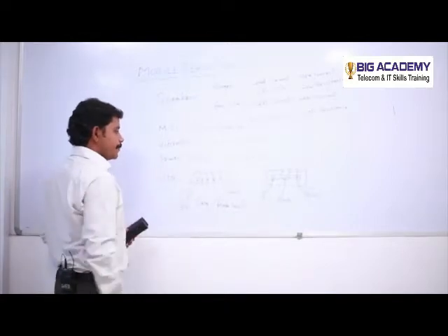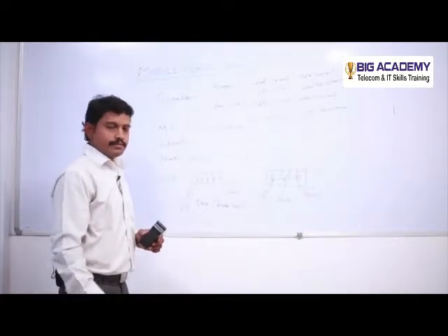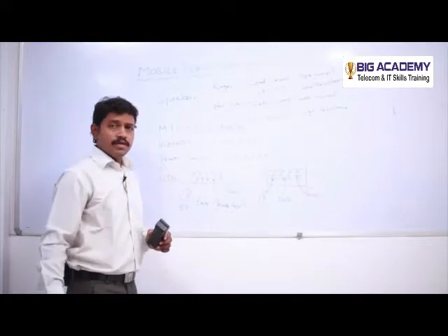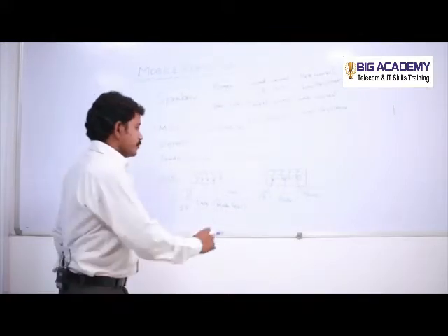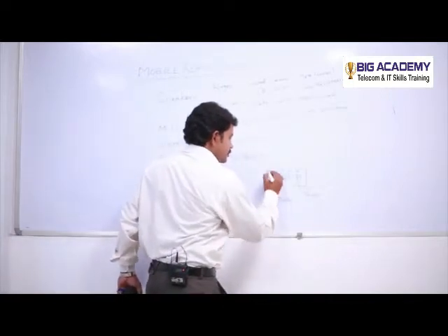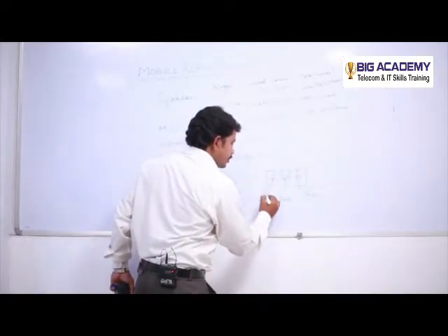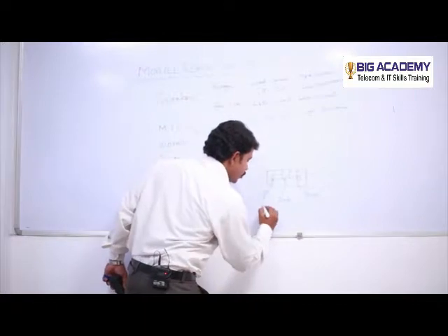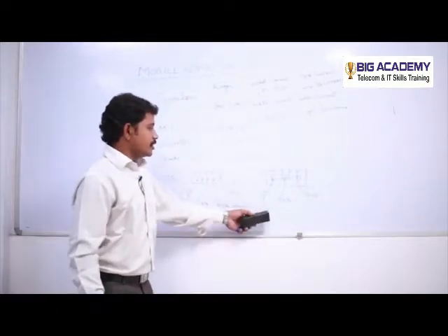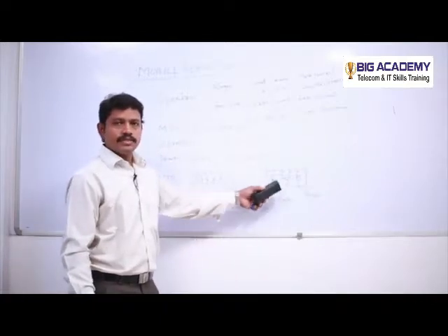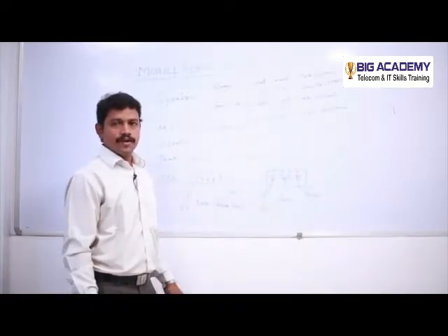If you measure this C-type connector, you will receive the 5 volt level. And in this, you can check it, which gives more than 3 volt. If it is more than 3 volt or 3.5 volt, this USB is working fine.